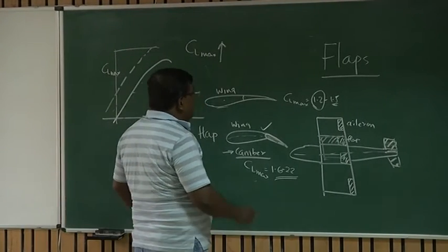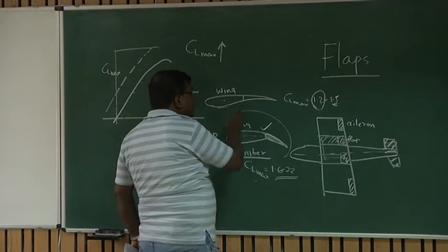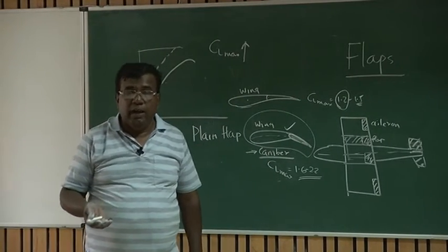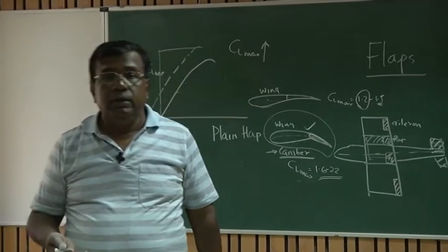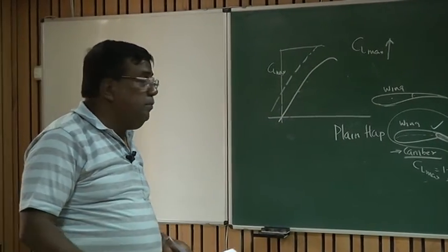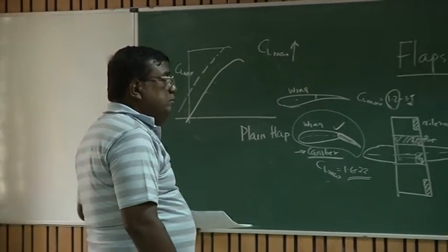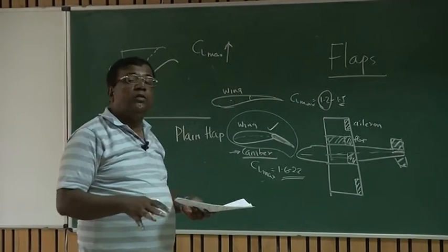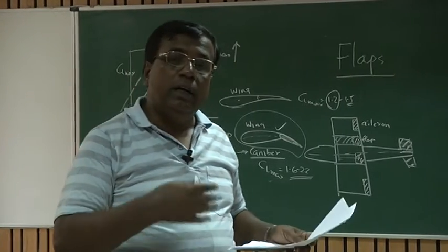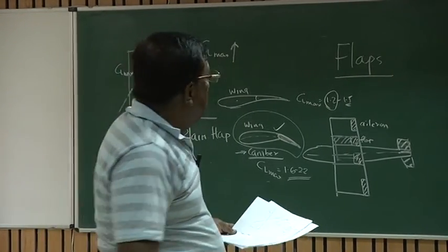So this is typically the principle of plain flap. Our Cessna 206 has this plain flap, and I have demonstrated I can deflect that plain flap 10 degrees for takeoff and 20 degrees sometimes, but for full maximum flap deflection, I am sure that now I have touched the ground. That is primarily used for increasing the drag to reduce the touchdown distance. Okay, so this is plain flap.